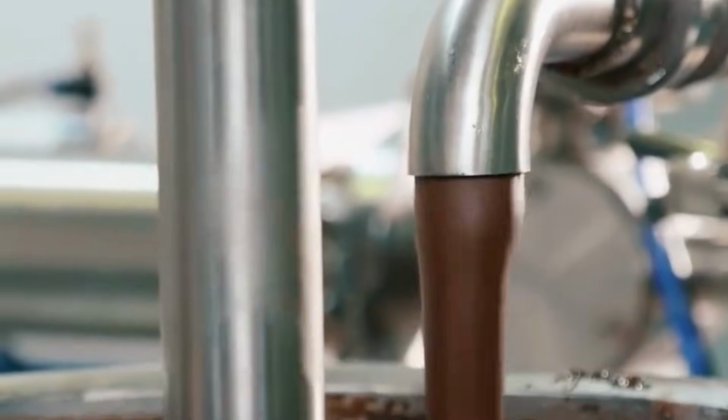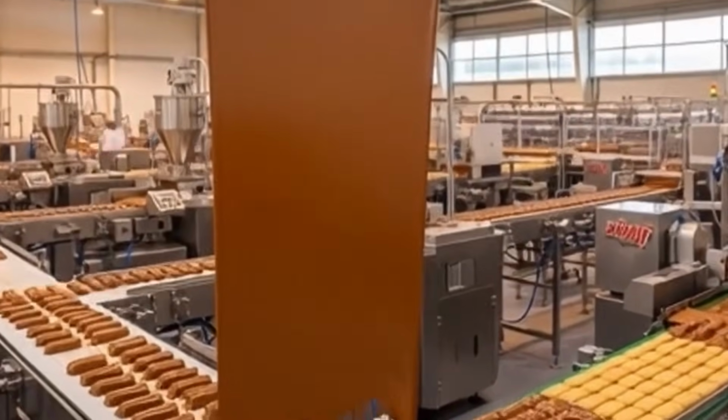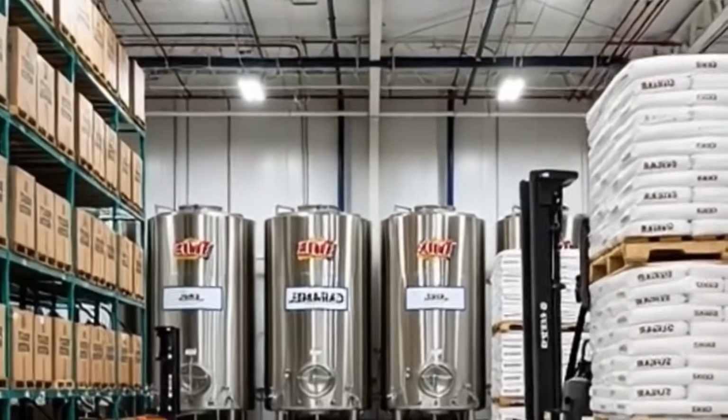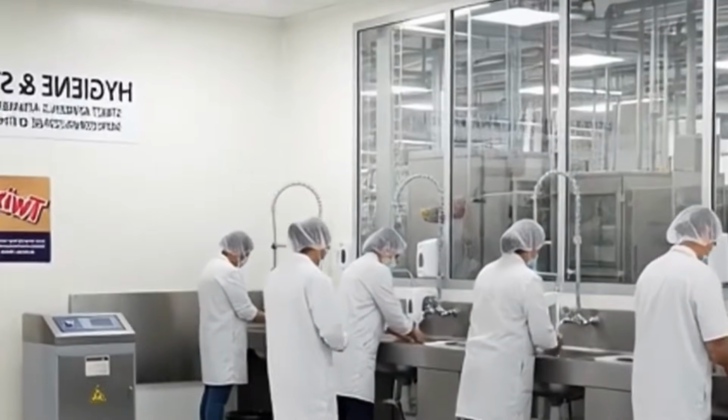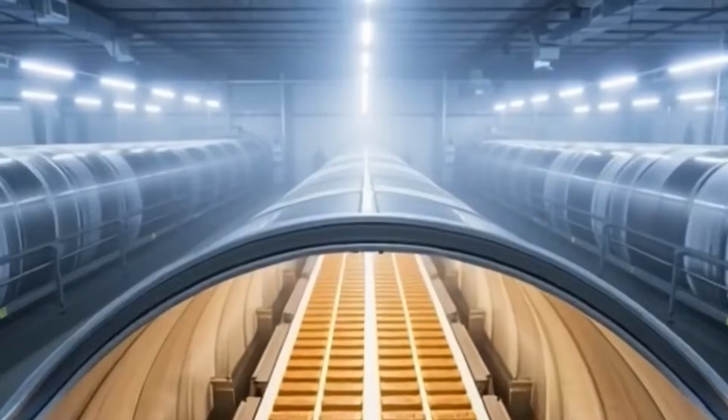The mixing cycle includes 2 stages: dry blending for even distribution of powders, followed by wet incorporation using medium speed agitation. The dough is formed to a target moisture content between 16 to 18% to ensure optimal flow and shaping characteristics. Upon completion, the dough is conveyed via a stainless steel auger system to a rotary molder.